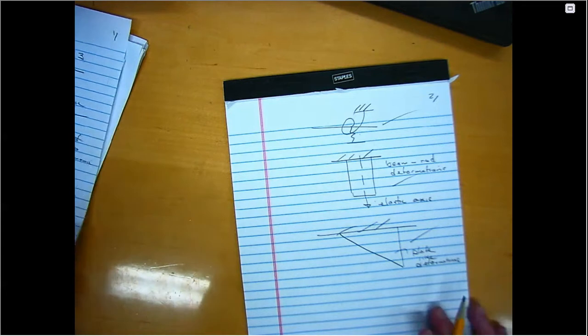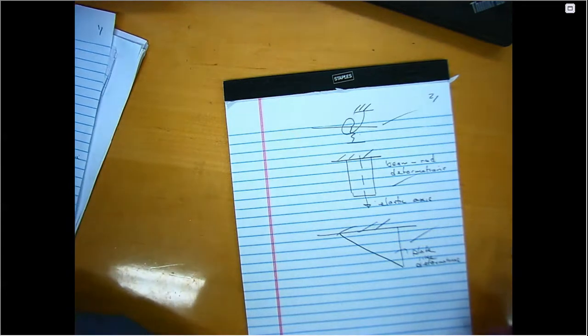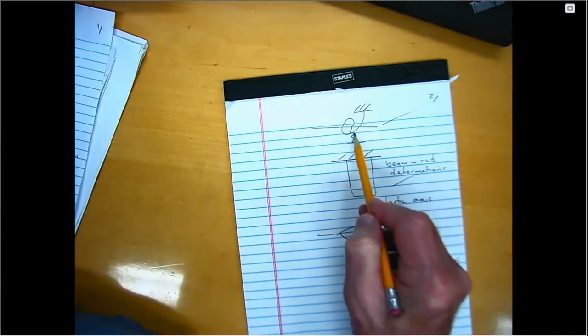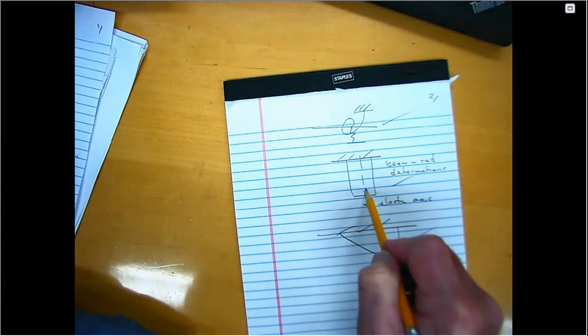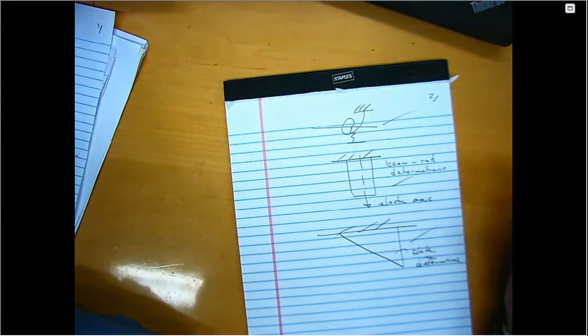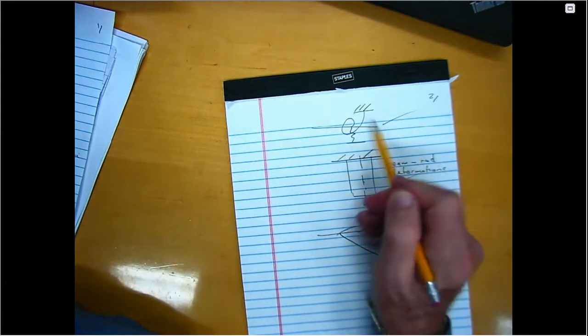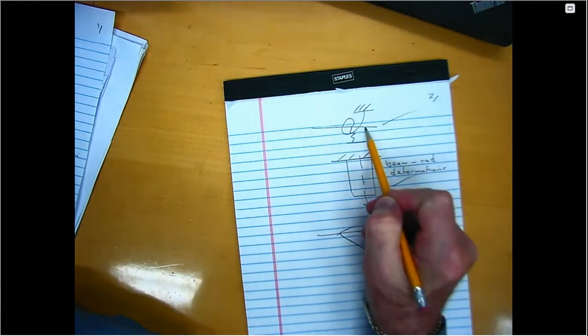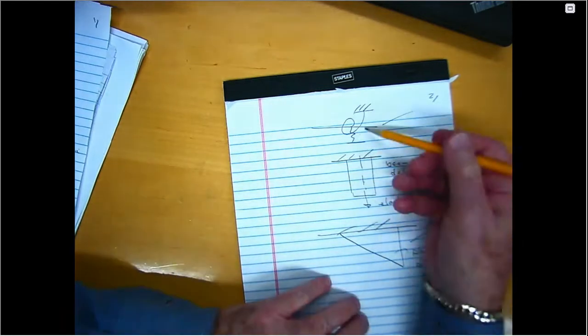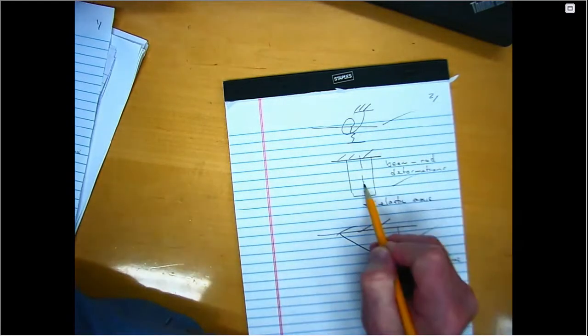It turns out, not surprisingly, that this model you can think of as a special case of this model. How's that? Well, this model has an infinite number of modes in both bending and torsion. But if I only keep one bending mode and one torsion mode, I have 2 degrees of freedom, and then the mathematics looks just like the mathematics here. The coefficients have a different physical interpretation, but mathematically these are the same if I only take 2 modes.